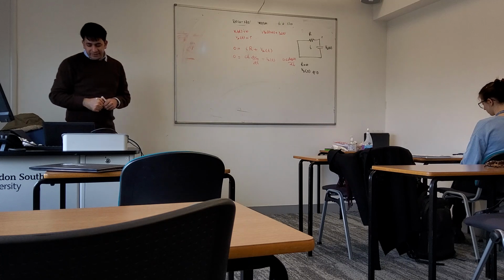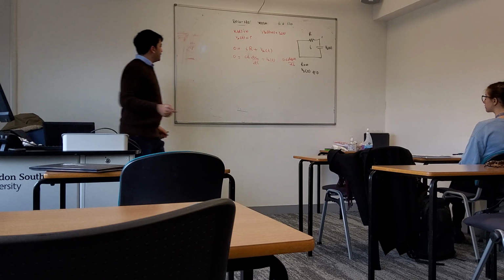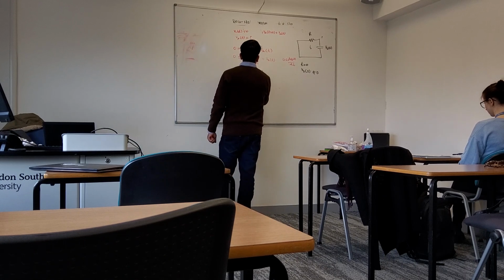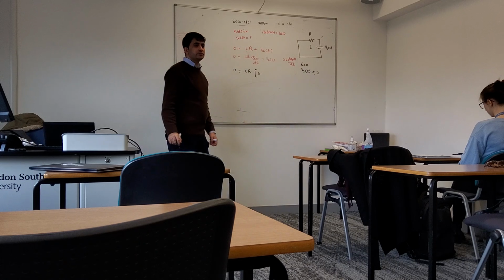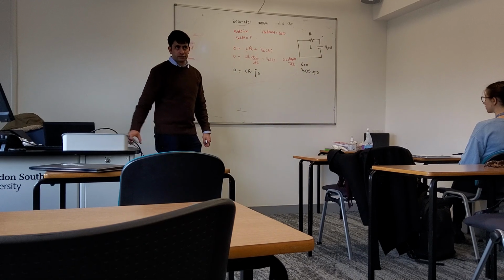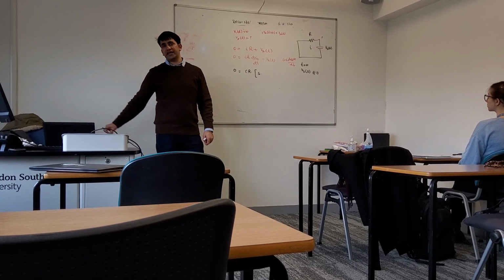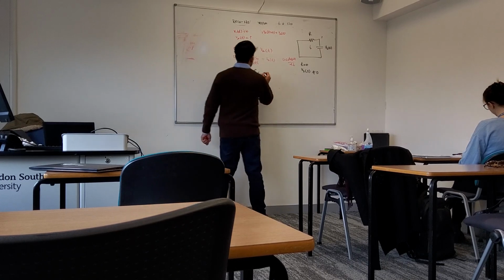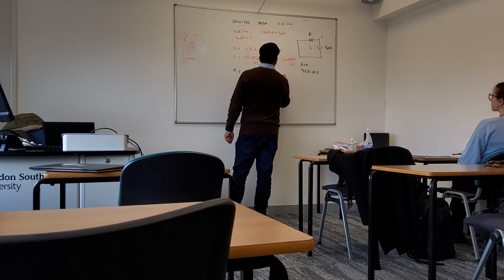Okay, now the next step is what we're going to do. We're going to apply Laplace transform, right? Apply Laplace transform, so 0 equals CR. Here the Laplace transform would be S. What is the Laplace transform for a derivative? S V2 of S, right? Minus V2 at time equals 0, right?